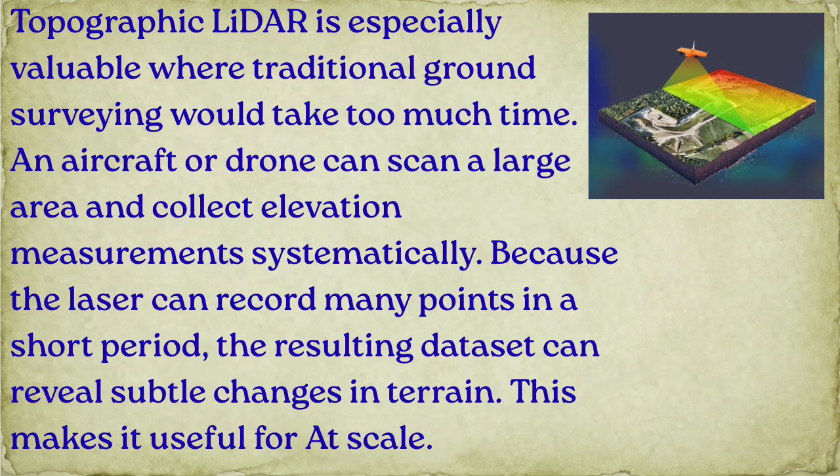This matters. Topographic LiDAR is especially valuable where traditional ground surveying would take too much time. An aircraft or drone can scan a large area and collect elevation measurements systematically. Because the laser can record many points in a short period, the resulting dataset can reveal subtle changes in terrain. This makes it useful at scale.